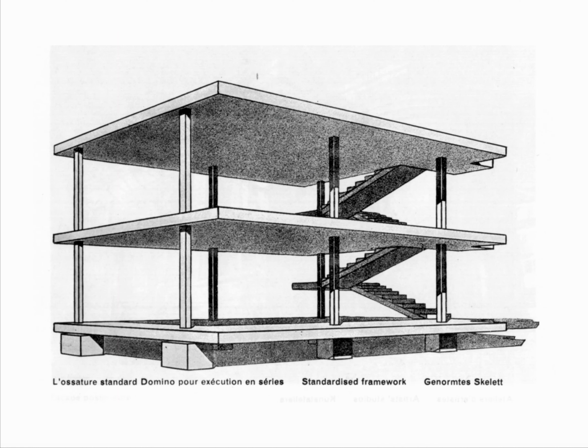Last time we talked a little bit about the Maison Domino and Corbusier's idea that he had depicted here of, instead of having bearing walls on the outside and interior bearing walls, things that then define the space, that both these open slabs and the columns allowed for a new way of actually thinking about building space, spatial arrangement, even building expression, as now we see that the columns are replacing the bearing walls on the outside, which allows the outside to be now more wide open and expansive.